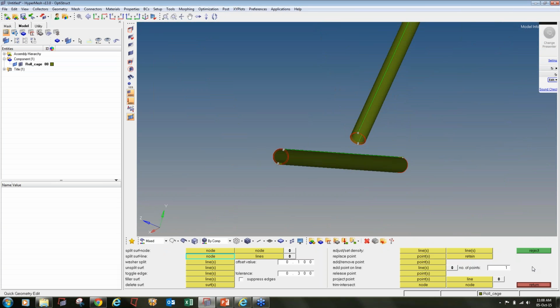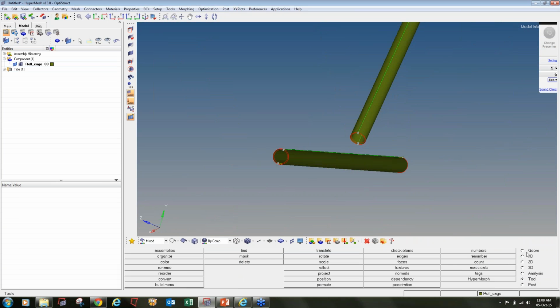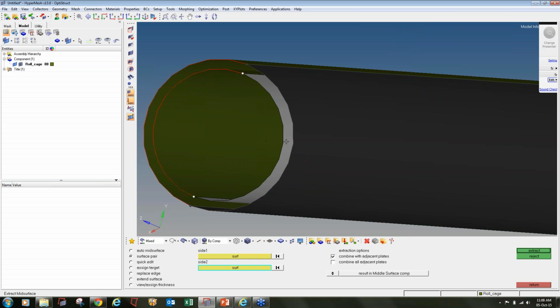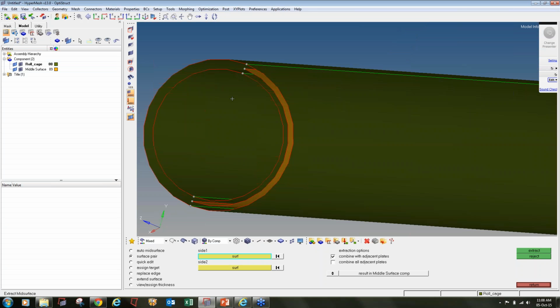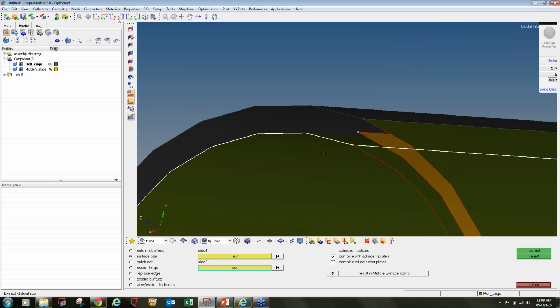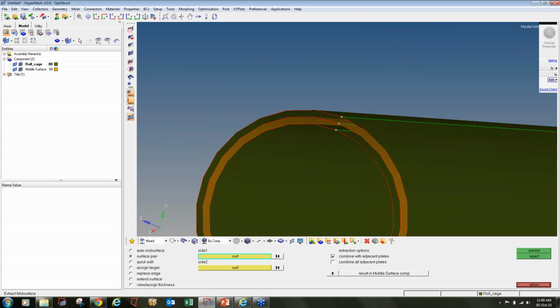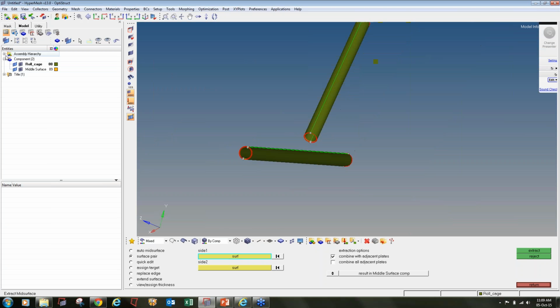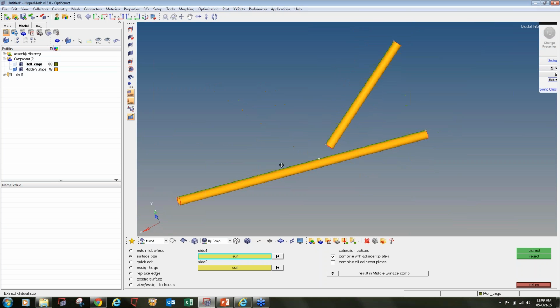Now the next step is I will go and create a mid surface. I'll go to geometry, mid surface, that is third column, fourth row. Select two surfaces and say extract. Similarly, these two surfaces, say extract. Here also these two surfaces, say extract, and these two surfaces, and click on extract. So now I will turn off this. So I have a geometry of the mid surface.